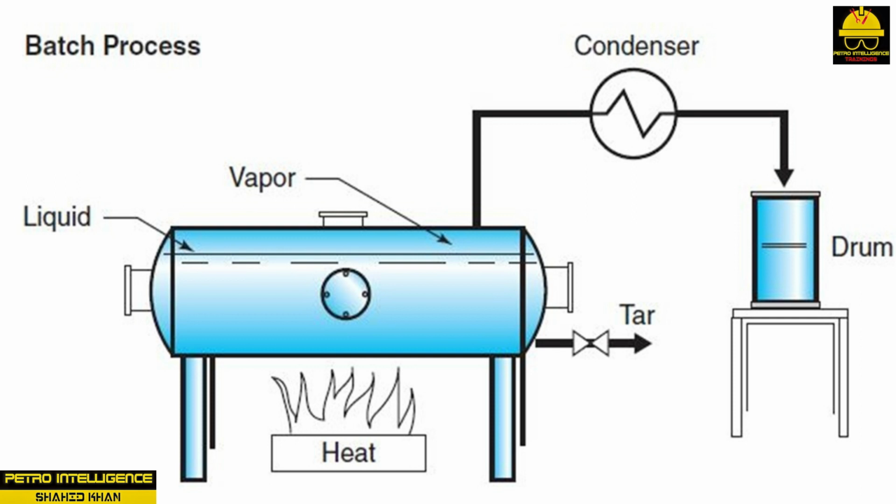At the conclusion of phase 1, the overhead line was switched to a new receiver, and the temperature was increased. When the receiver was full, the process was repeated, and the heat was increased incrementally until the batch run was complete. Product quality during batch distillation operations was very poor. Frequent receiver changes wasted time and money.